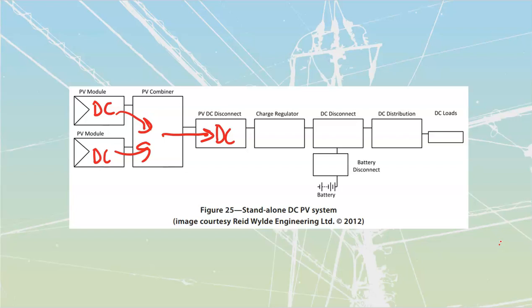But oftentimes they will also chop holes in roofs with chainsaws and with axes so that they can control the flow of smoke and heat and stuff like that. It helps them with the fire. What happens is if we've got a bunch of these on this roof, all of these are going to be generating. The sun is still out, possibly, when this building is on fire, and those systems have not burnt, so we need to have a way that they can rapidly shut them down. There's a pile of rules about rapid shutdowns inside of your code that are there to save lives. They talk about how we need to have these systems identified so that they don't just start chopping holes in the roof and chop through hot cables that we're feeding down through there.